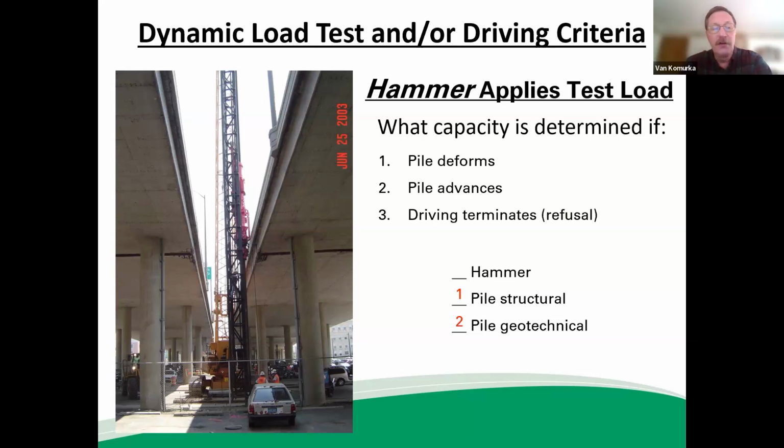What if the driving terminates? You've stopped moving the pile, as in the case of a static load test where the jack is maxed out. The pile isn't moving. The pile is resisting everything the jack can put on it. In this case, driving terminates, practical refusal. The pile is resisting everything the hammer can put into it.